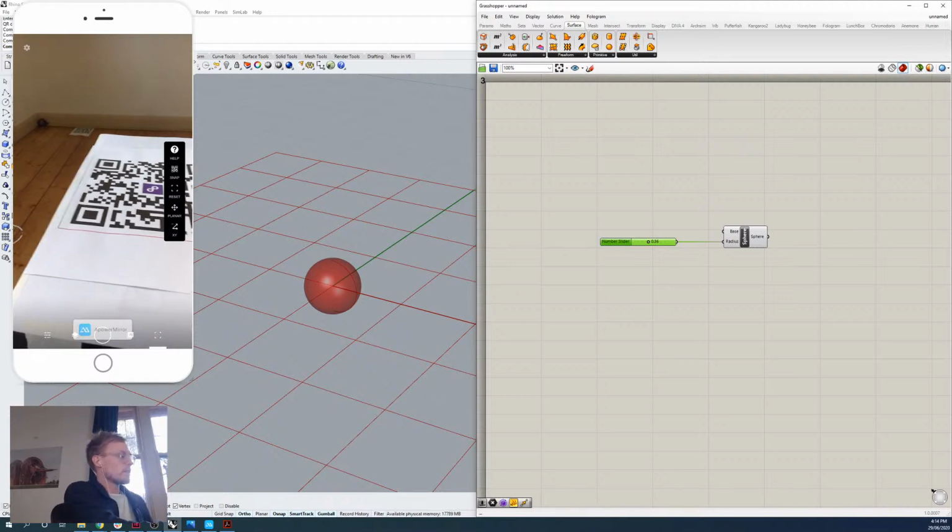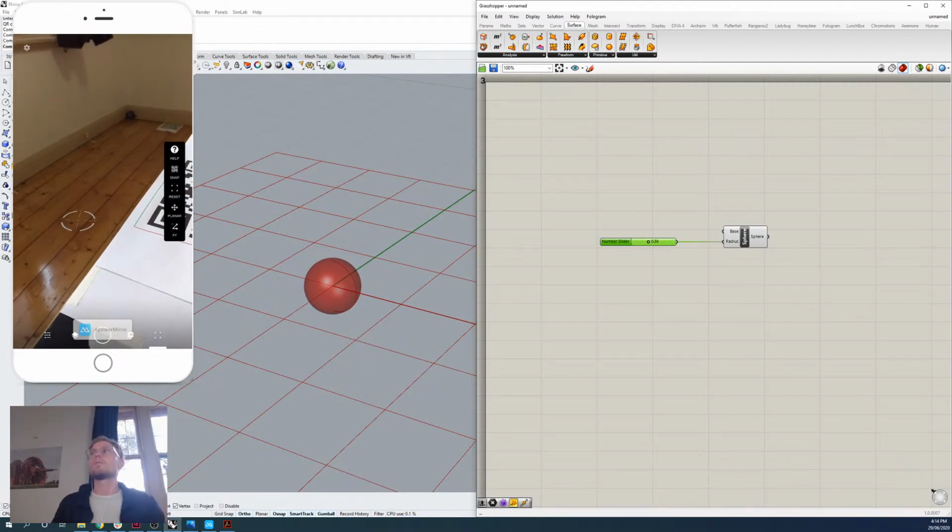What we can quickly talk about is the problem I was just discussing before though, and you'll see right over there, I don't actually have a sphere appearing in my output. So despite the fact there's clearly a sphere appearing as a preview in Rhino, and I've dropped a sphere onto the canvas in Grasshopper, I don't see that in my Fologram device.